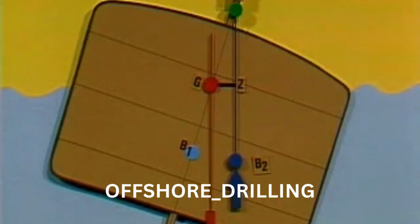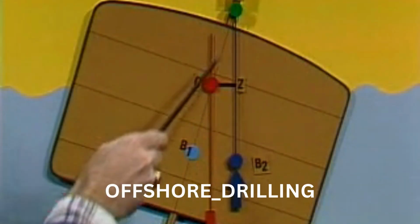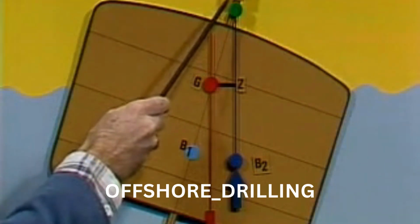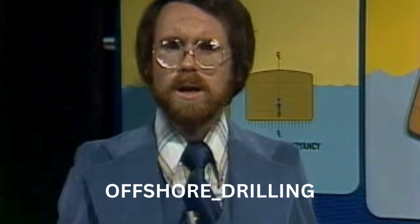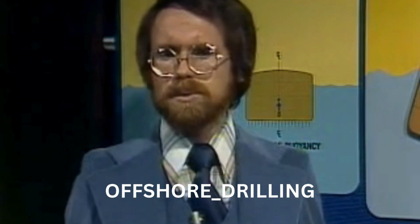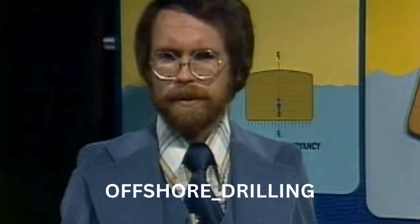As I said earlier, M is located at the intersection of a vertical line through B2 and the center line of the vessel. M is the highest point to which G can rise and still permit the vessel to have positive stability. It is called the transverse metacenter and is abbreviated as M. Let's talk about the equilibrium of a vessel for a minute. Equilibrium can best be described as one of three conditions: stable equilibrium, neutral equilibrium, or unstable equilibrium.